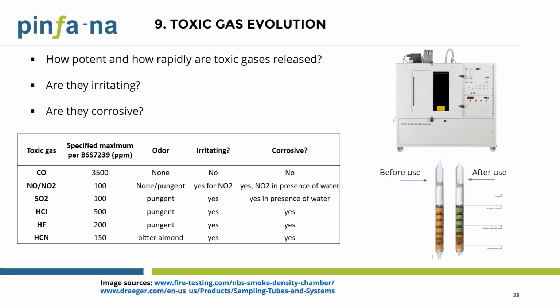The advantage of the Draeger tube method is its simplicity, as it doesn't require complex equipment, so it can be cost-effective if not many samples are to be tested. And also fast, because no user calibration is needed, and the result is immediately shown. The gas detection method using FTIR can also be very useful because it can provide a time evolution of multiple toxic gases simultaneously to study a fire process, and it could be cost-effective as well if a large number of samples are to be analyzed.